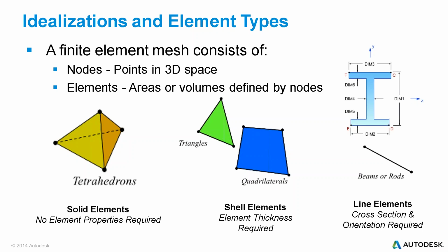If you look at something like a surface model, Nastran identifies that as a shell element. So we're not limited to just working with solids. We can also work with those surface models or shell elements. Breaks those down into triangles or quadrilaterals. And if you're looking at something like a frame structure, be it a machine frame or even a building frame structure, you can simplify it to break it down into line elements, which are then interpreted as beam or rod and connector points. And the goal of all this is to get accurate results.